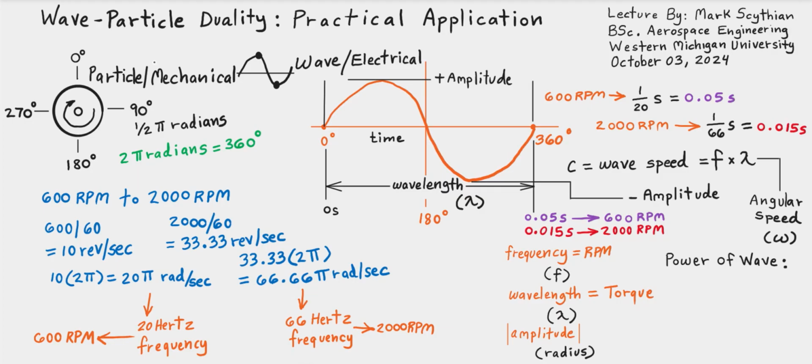So it's pretty responsive today with the computing power. So there'd be a secondary high pressure ABS booster, not just for anti-lock but anti-skid, that would kick in and then graduate a pulsation on those three wheels to match them to the slowest wheel, because the sine wave graph for the three wheels is going at a higher frequency RPM than the others, and so it's just a matter of slowing that frequency down by high pressure secondary automatic braking, like pulsation.